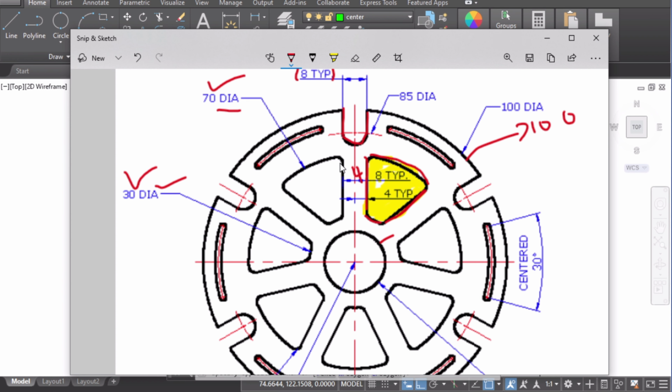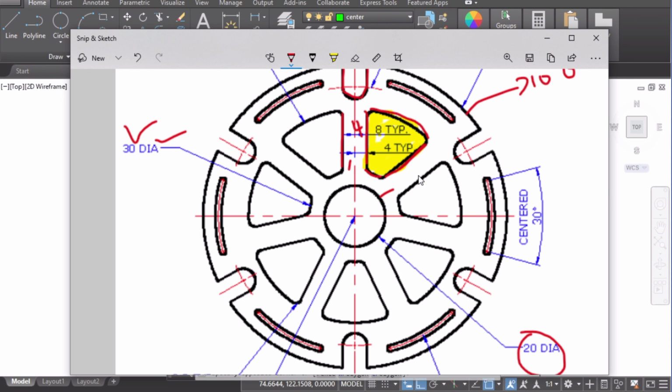If you observe it carefully, you can see there is another line over here. You can offset 4. And if you take the pairs, this is the first pair, second pair, and you can see another pair of the same kind of line. This is third and fourth, fifth, sixth, and the last one. Here you have another parallel lines. So what I'm going to do is construct the first pair and make an offset, and then I will make an array so that I can make 7 pairs, and we can easily identify this line. Okay, let me show you how we can do it.